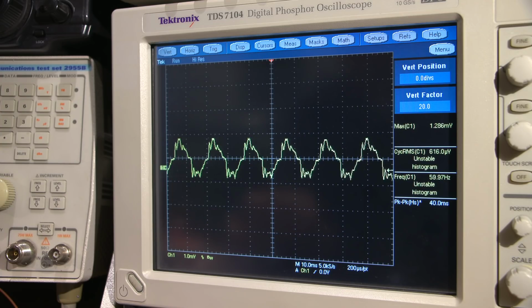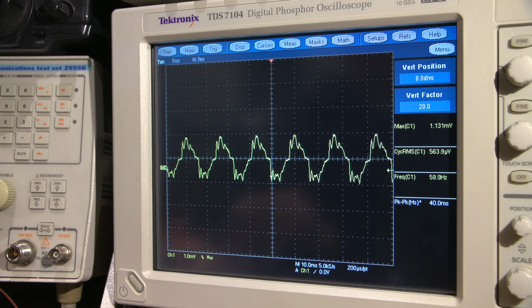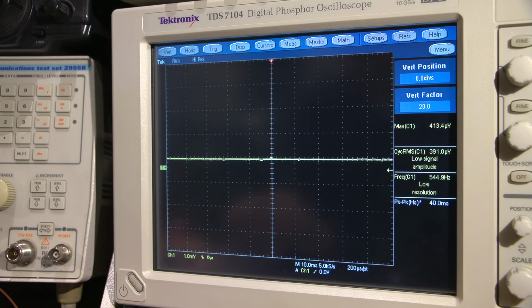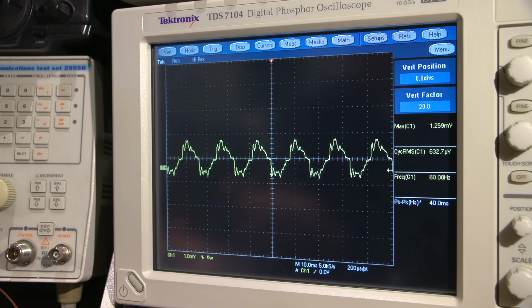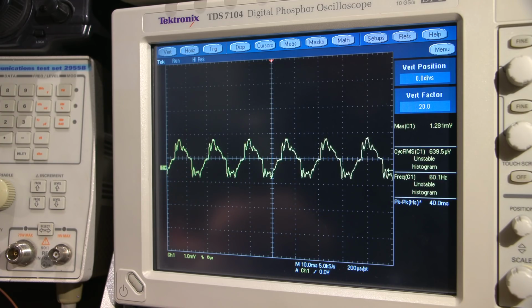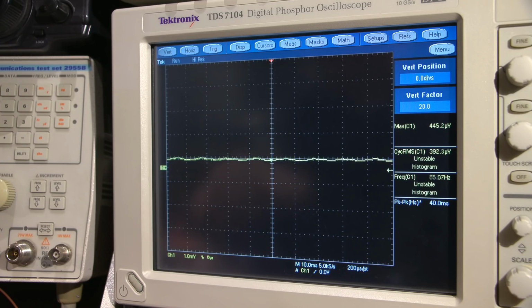Right now my probe is just open. I had it grounded out. This is with the tip grounded out, so this is just picking up random noise. So what I'm going to do is put this right here, and as you can see, I have a little bit of signal. Now if you look down here, you'll see that I'm at about 1 millivolt per division. That's the sensitivity. And there isn't enough here. This is usually as low as most scopes go.